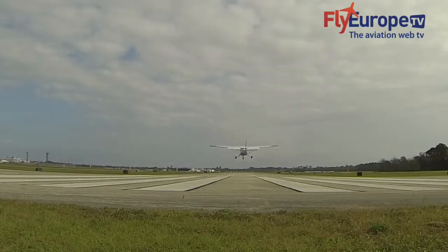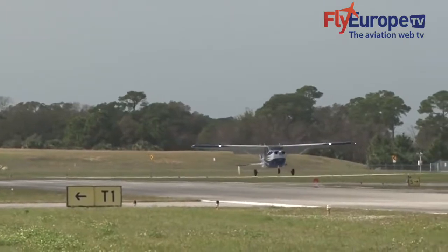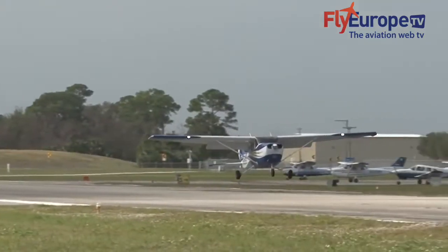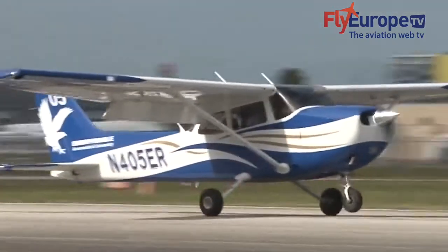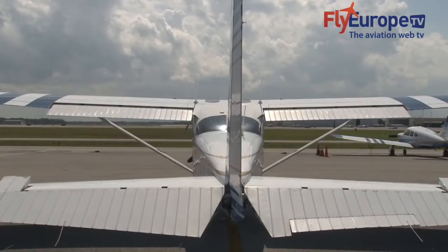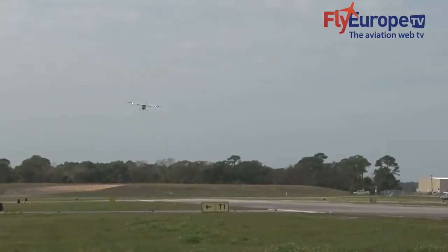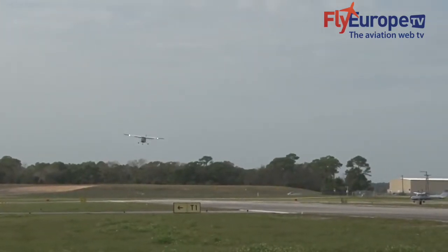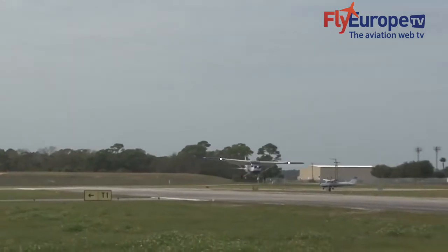We saw how pilots can control the lift generated by the wings by changing the aircraft's airspeed and angle of attack. However, most airplanes come equipped with one or more additional ways for the pilot to manipulate the wings and, in essence, change the shape of the wings. These are called high-lift devices, the most common of which are trailing edge flaps, or just flaps for short. High-lift devices, such as flaps, are designed to increase the lift and drag generated by the wings at low air speeds. Flaps are particularly important for the approach and landing phases of flight.